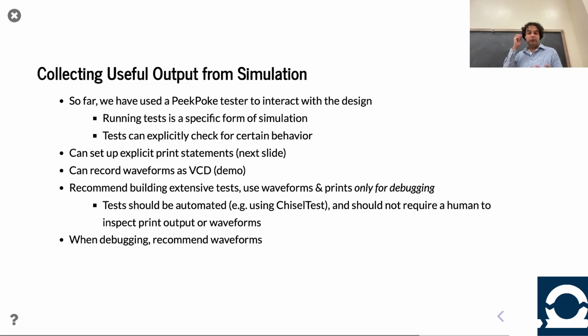What's cool about that is, as you're debugging, you run the simulation once, and you can trace your way through the waveform. So you are navigating that waveform. You only need to run simulation once. With printf debugging, typically you put a printf in there, see the value, and think, oh, that's surprising. What about this other value? You need to add another print statement, another simulation run, and you're repeating. So waveforms are typically a better practice to use for hardware design, but guess what? There are some times where prints are really handy, so we teach you both.